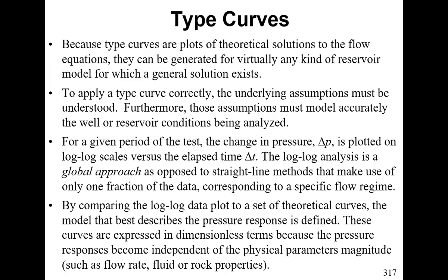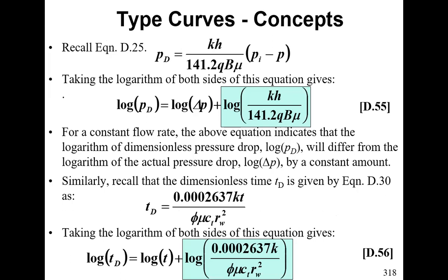And some things I'd like you to take note of here is for the type curves, you're plotting your test data on a log scale, and again, you are looking for a match to a set of theoretical curves that have been prepared in the form of graphical solutions. So I'd like you to just take note of this.